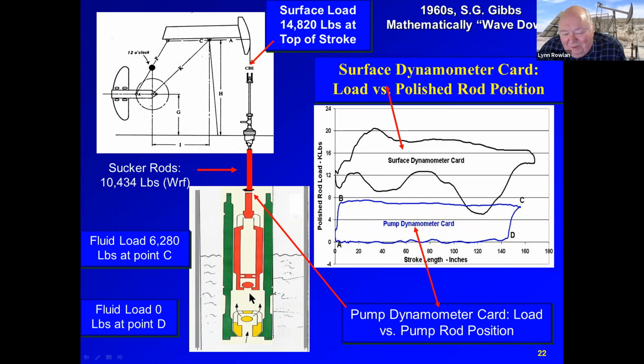And the well might be helping a little bit. So the difference in pressure from above minus the pressure from the well is the differential pressure acting across the pump. And it's fairly constant because that line's fairly flat. The plunger is moving up from here to here, and well fluids are entering the pump chamber through the intake valve. Then right here at the top of the stroke, both balls go on the seat and we compress the fluid. And right there at point D, what happens? Well, this traveling valve pops open and there's no load.